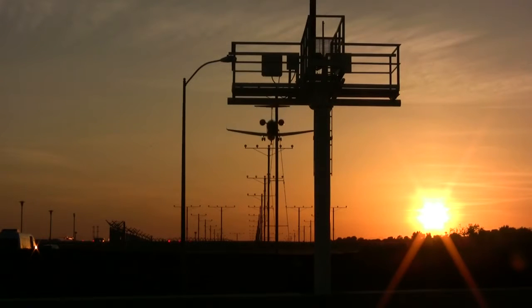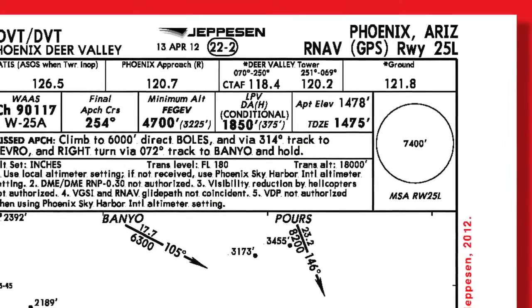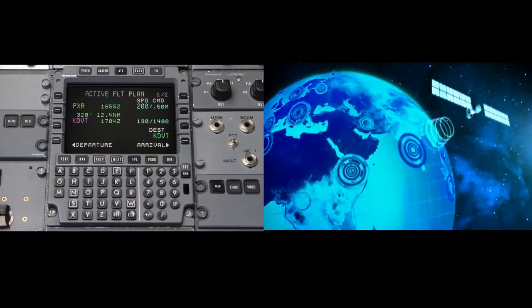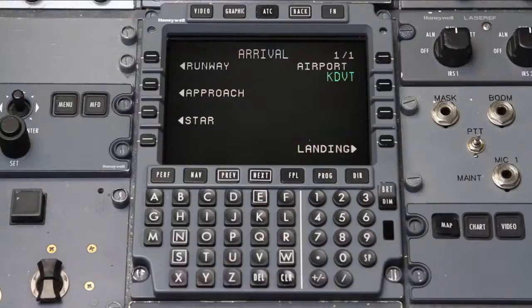Prior to the development of SBAS, GPS was not able to provide the accuracy or integrity to achieve Cat 1 minimums during approaches. The FAA and Department of Transportation began development of WAAS in 1994 to allow precision approaches, and in 2003, WAAS was activated for public use. An RNAV approach with LPV minimums combines the FMS navigation database with SBAS signals from GPS satellites to produce an approach that closely mimics an ILS.